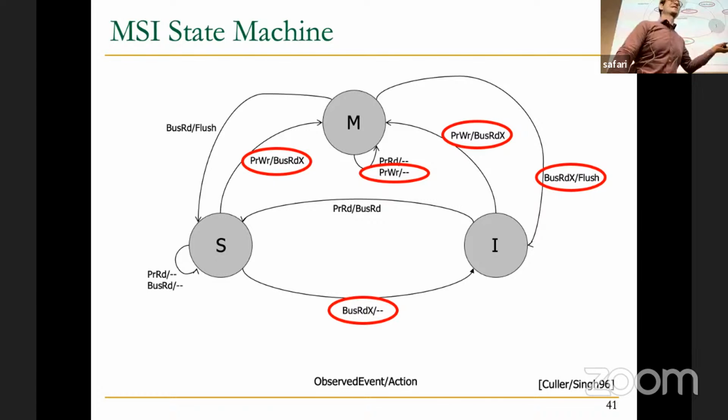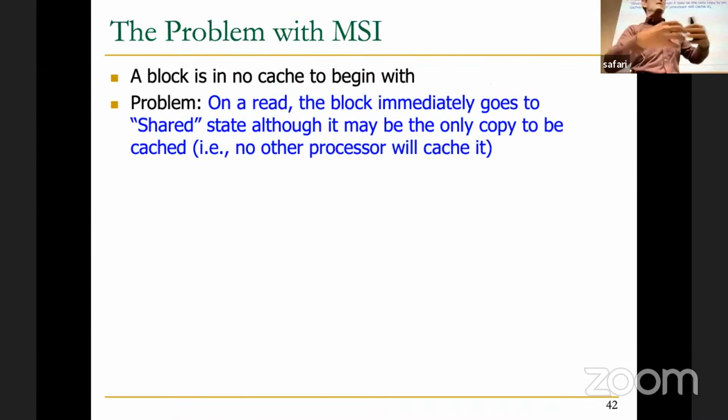That's why, as we mentioned in the last class, a lot of the bugs that happen in real processors are due to coherence or memory ordering. Because these are not easy things to get right, especially if you have a very high frequency, high speed pipelined bus implementation. Even if you have a bus. Assume that you start with a bus even. But normally we don't even have a bus today. Well, we have a bus, but we have other interconnects as well. And our shared memory region is bigger than just the domain of a bus today.